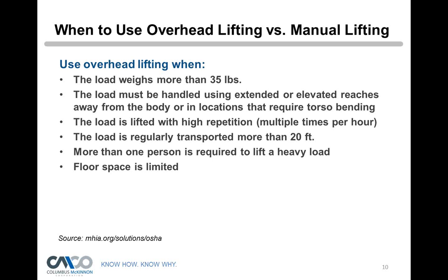Repetition, so multiple times per hour. Here in Detroit, we're located in Howell, Michigan. We have mostly an automotive base, and some of the tack times for an application is 70 times an hour. So things like that, that's what you'd like to have an assist of some sort helping you with the process. When the load's transported a long distance, something more than 20 feet, that's another red flag where you'd probably want to use an overhead lifting application.